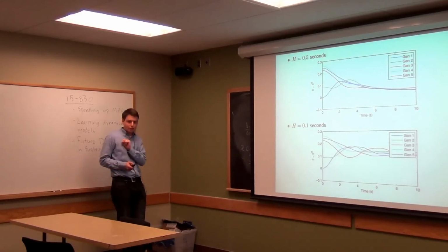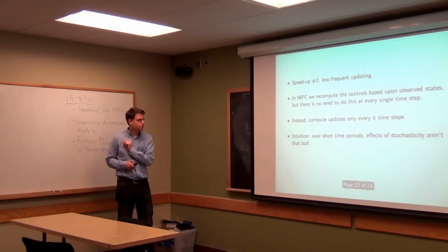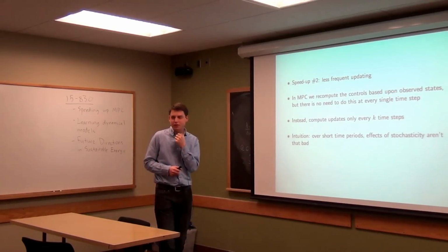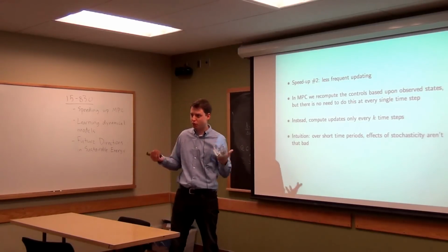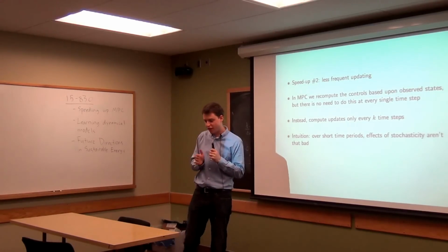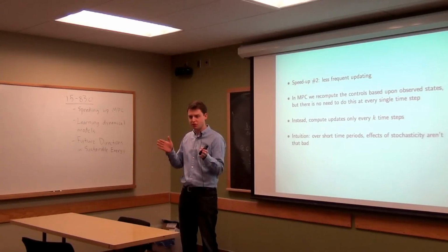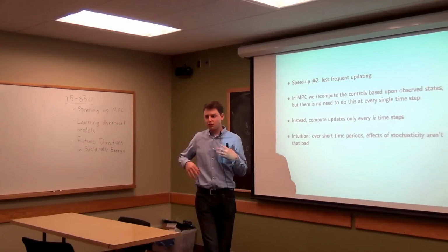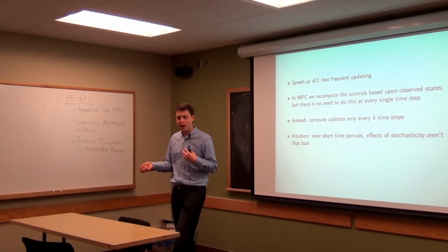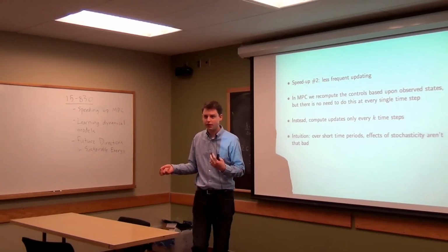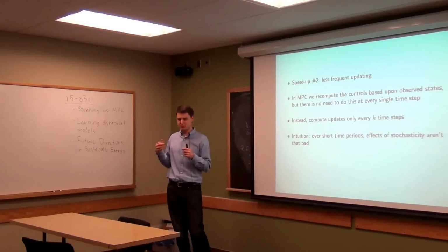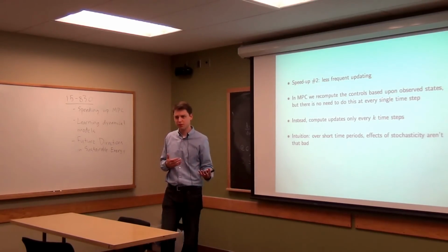So that's idea number 1. Idea number 2 is that there's no real reason. I mean, MPC, as I put it before, was the idea that you optimize something, you take the first action, then you see what happens, and you optimize again. And there's no real reason you have to do that every single time, right? In fact, our time step was somewhat arbitrary, what we picked for our time here, right? I picked 0.01, but that's just because I'm discretizing some real-world system.